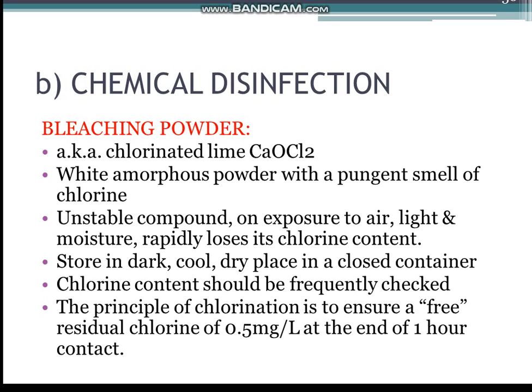Bleaching powder should be stored in a dark, cool, dry place in a closed container that is resistant to corrosion. The chlorine content of bleaching powder stocks should be frequently checked. The principle of chlorination is to ensure a free residual chlorine of 0.5 mg per liter at the end of 1 hour contact. Highly polluted and turbid waters are not suited for direct chlorination.